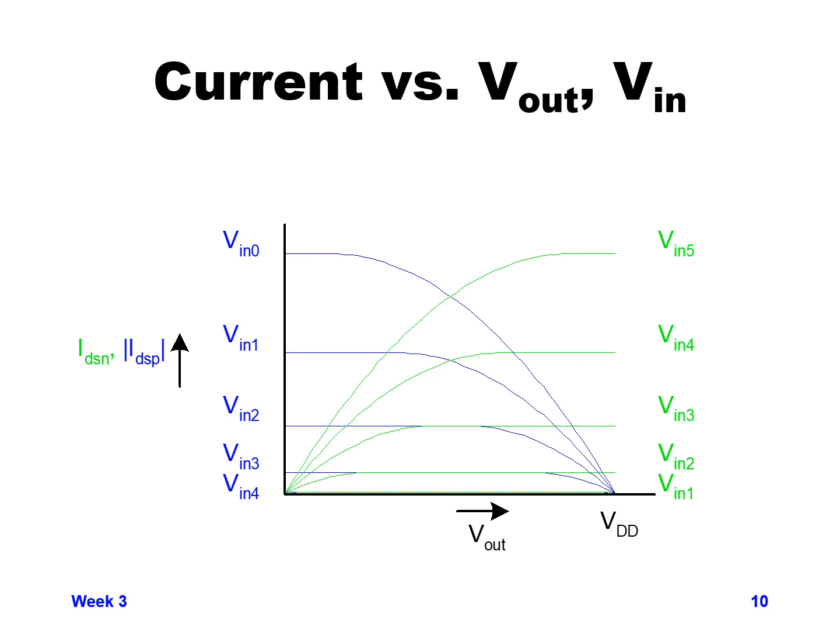So this graph here is showing if we took the previous foil and instead plotted the PMOS and NMOS both in the same quadrant. Instead of plotting the PMOS device relative to the drain and going negative, we plot it relative to VDD and go to ground.